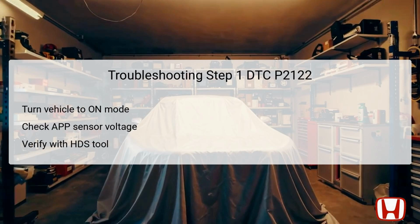The first troubleshooting step in diagnosing DTC P2122 begins by turning the vehicle to on mode, which activates the electronic systems without starting the engine. Next, using the Honda Diagnostic System (HDS), technicians should check the voltage output from the APP sensor, ensuring it meets the expected operational threshold. The specific test involves observing the current conditions against the defined parameters. Ideally, the voltage should hover around the approximate operational threshold.